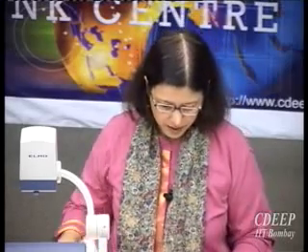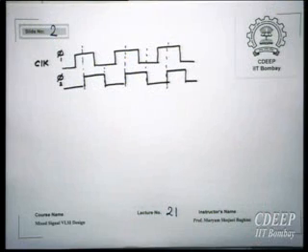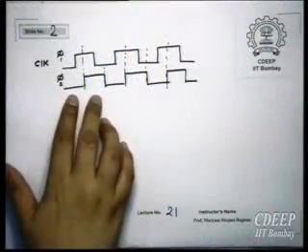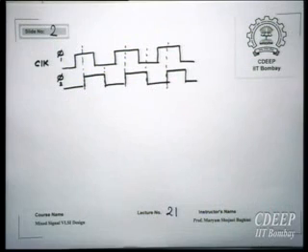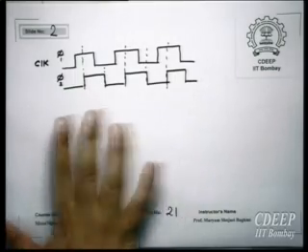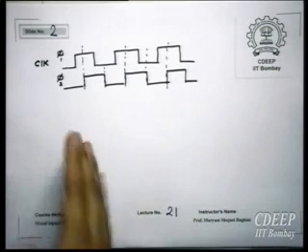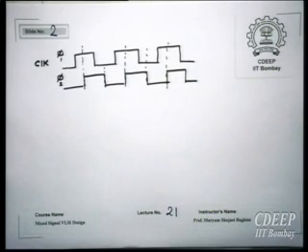So the first circuit is called a delay lock loop. It is based on a PLL and locks at a particular delay at a given frequency. Therefore, here we consider frequencies constant and it just locks at different phases. It is not very difficult because you consider a type 2, for example, or even type 1, actually, for the phase not to be 0, type 1 will do.